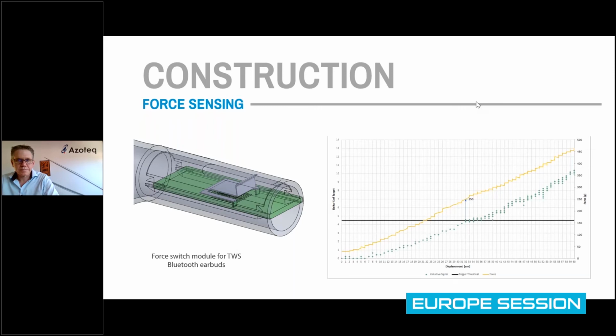That's very great to hear. So you also mentioned choosing a capacitor to set the correct resonant frequency on this inductive sensing. Did I hear it correctly? Yes. You want to get it as close as possible in the mutual inductance to the resonant frequency where the two coils are resonating, and for that we use an external tuning capacitor.